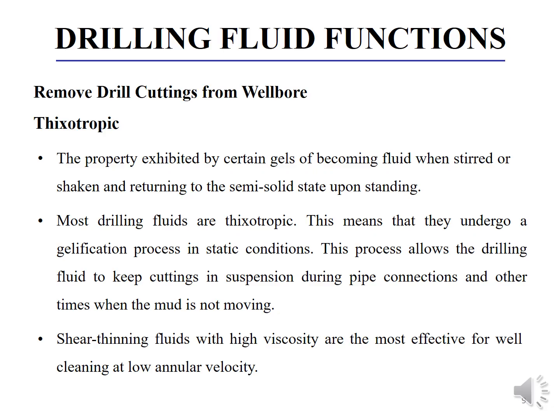Next is the thixotropic property. This property, which is exhibited by certain gels, is becoming fluid when stirred or shaken and returning to the semi-solid state upon standing. So most drilling fluids are thixotropic. This means that they undergo a gelification process in static conditions. So the mud should always be in a circulating motion. This process allows the drilling fluid to keep cuttings in suspension during pipe connections and other times when the mud is not moving. Shear thinning fluids with high viscosity are the most effective for well cleaning at low annular velocity.